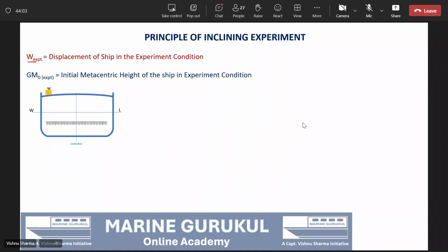And to measure how much the ship will incline when this weight is shifted, to read the exact value, you use a pendulum, so a pendulum is mounted. You keep the length of the pendulum a little down. You see my pendulum is overshooting, why? Because when the pendulum inclines, it should not fall short of the graduations. Which length of the pendulum will be counted as the length L? It will be the length of the pendulum up to the graduations, not up to the tip.